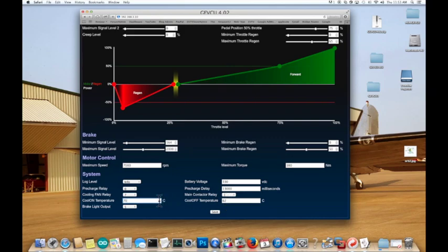And so once it hits 70, it's on for quite a while, unless you get down to 55. You can moderate that. Brake line output number 5 is simply we're going to switch on one of our outputs whenever we have more than 10 newton meters of regenerative torque. And this is as we go down the road, if we use our throttle to apply regenerative braking, we're going to slow down quite dramatically.